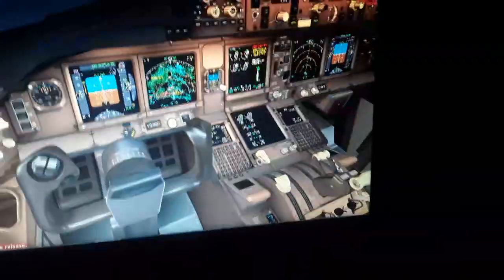So you have to anticipate that when you're flying. Anticipate the thrust lever's position and the thrust you need before you're gonna need it. So you actuate or adjust the thrust lever's position and give a command to the FADEC.